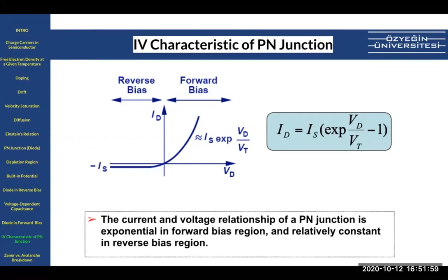When you use the ORCAD in the lab, sometimes you will be using non-ideal devices. And those non-ideal devices are actually designed, taped out, sent to fabrication, they come back, they get measured, and the parameters are found, and those parameters are injected into the simulation. And that's how these simulation tools are helpful with simulating these circuits.